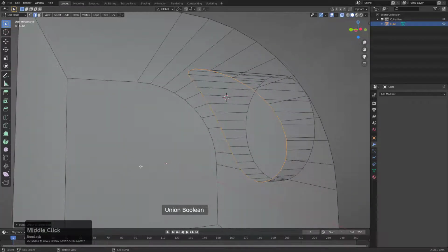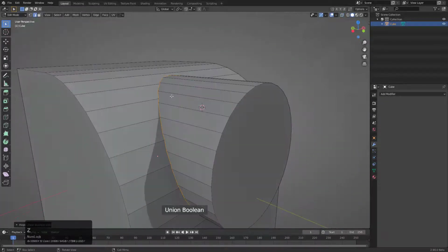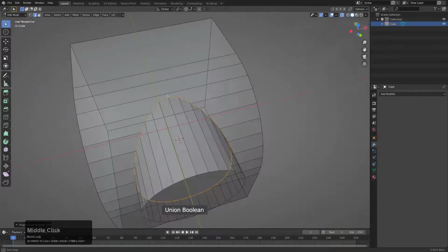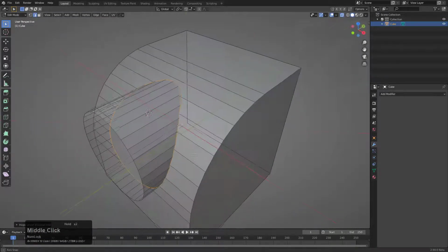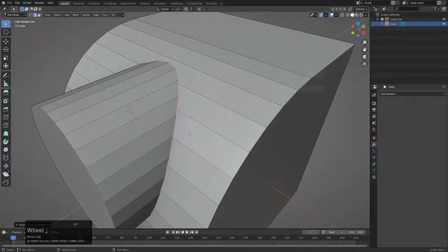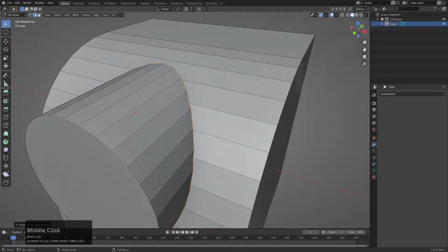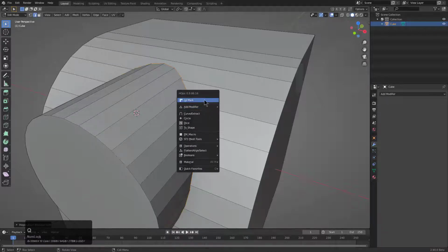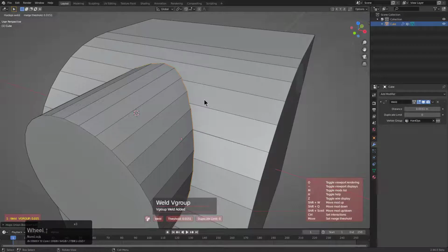And we know it's a union because there's no mesh on the inside and it's connected. But the best part of doing these things in edit mode is it does select a boundary, which I've always loved. So let's say we want to actually clean this geometry up, just this area utilizing weld. Well, by going in here and basically Control Shift clicking mark, we can go under weld, and by scrolling the wheel, we're actually helping these connections get made.